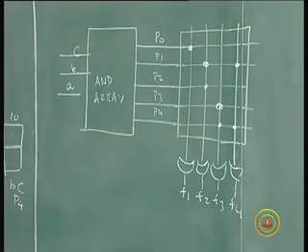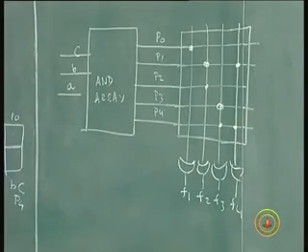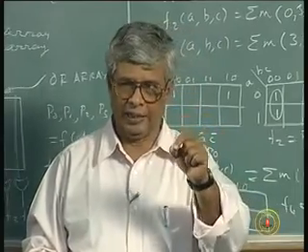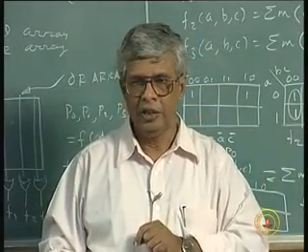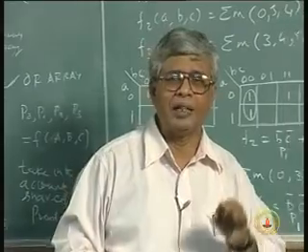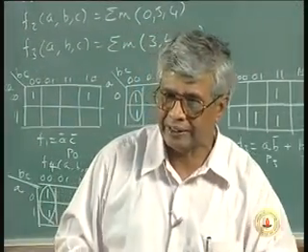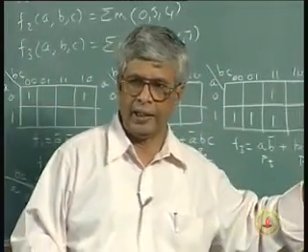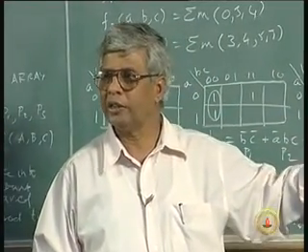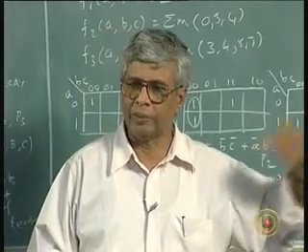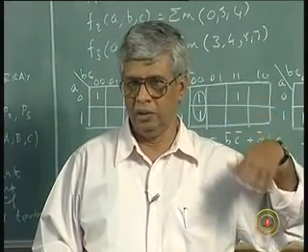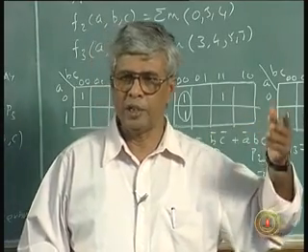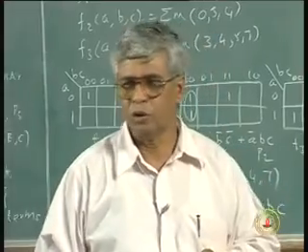So we have the advantage: the size is smaller, the AND array size is smaller, and not only the number of gates but the size of those individual gates, the number of inputs to each of these gates, is smaller. This will be significant if the number of inputs is large, which is the case in practical systems. Just because you take a simple example in class, which can be completed in a short time, drawing any diagram on the board, does not mean all systems are like this. These are only conceptual diagrams. In a real design, you will have many more input variables, and so the number of product terms, if you want to do a ROM based design, increases exponentially, explodes.